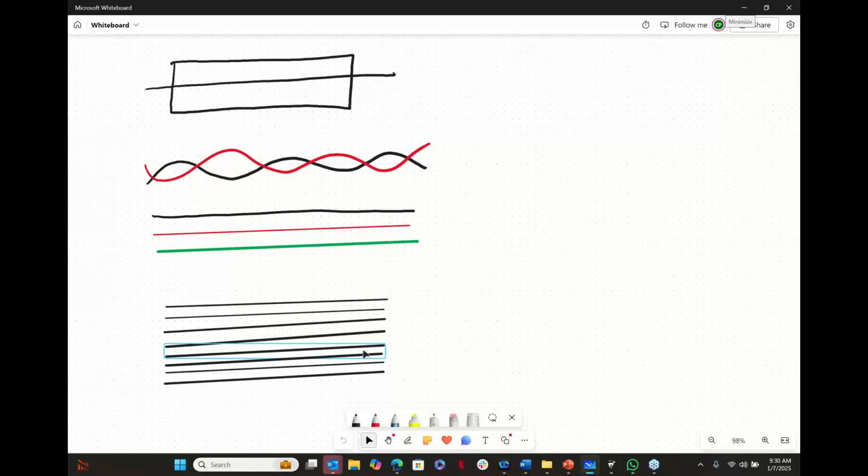So anytime you have 2 conductors that run parallel together over a distance, they will naturally form an electromagnetic field. That electromagnetic field gives you a constant impedance all the way through. What a TDR is looking for is anything that interrupts that constant impedance. Now, you could say anything that interrupts the relationship of the conductors to each other, and while that is partially true, there's a little bit more to it than that.